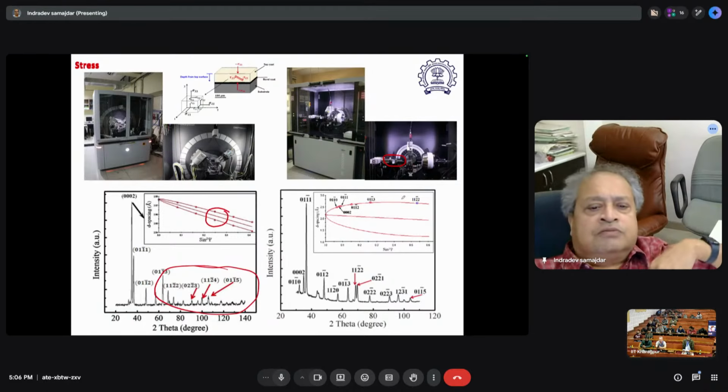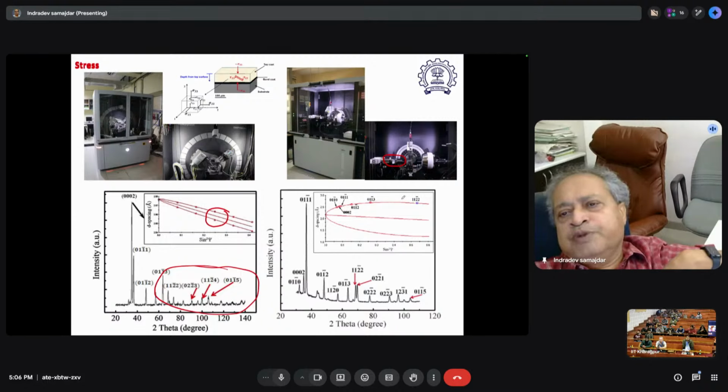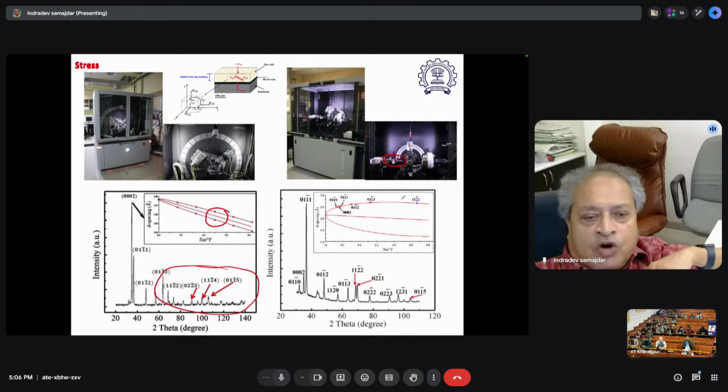A word of caution. There are algorithms for identifying XRD peaks automatically. If you are using a commercial algorithm, best is to use the Bruker's one. But none of these algorithms work very well. So peak shift identification needs manual intervention. So I normally get the stress done in one swoop. Otherwise, you are heading for a problem.